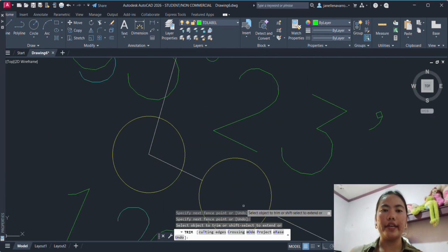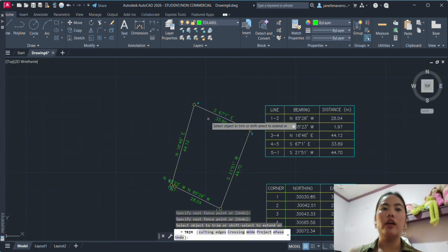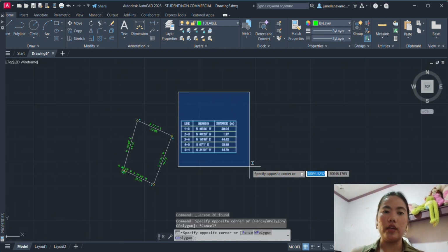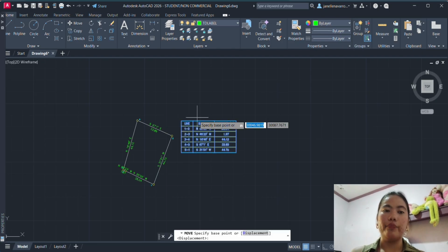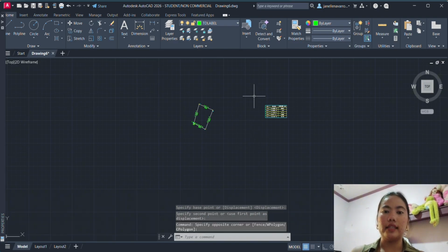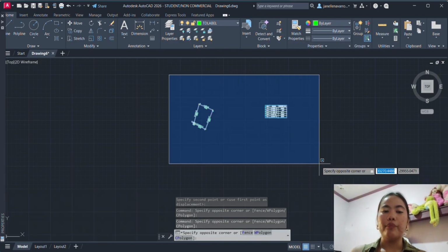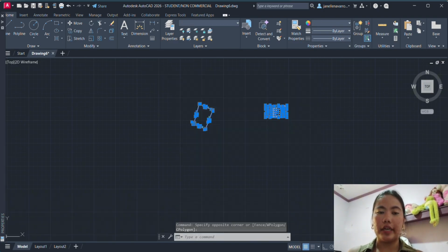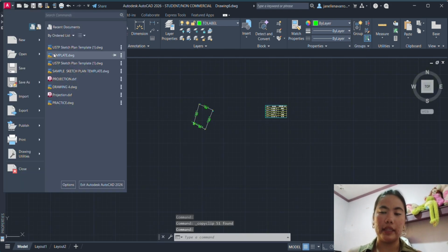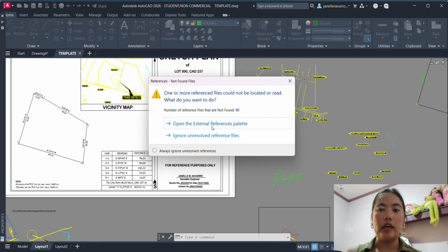So using TD create, I selected the boundary points of the parcel in their proper sequence, like point 1, 2, point 3, and point 4. The software then automatically generates the technical description based on the selected boundary points. I also specified the desired size and dimensions according to the required format to be applied to the sketch plan.